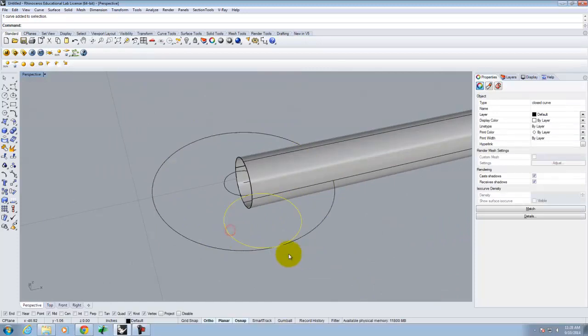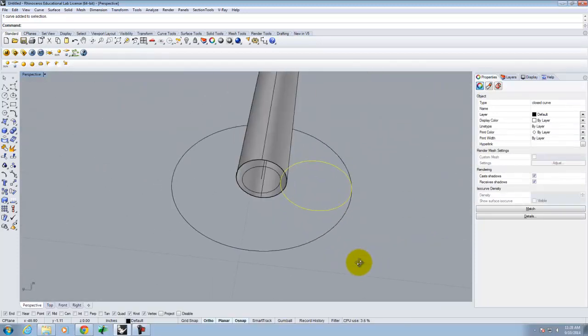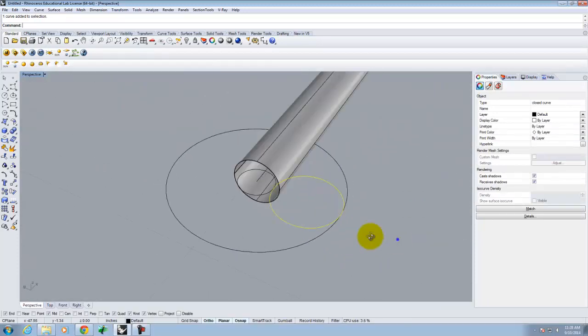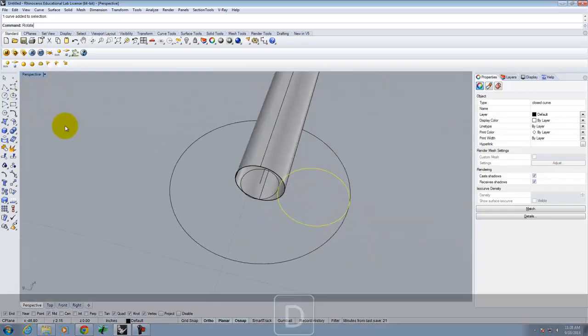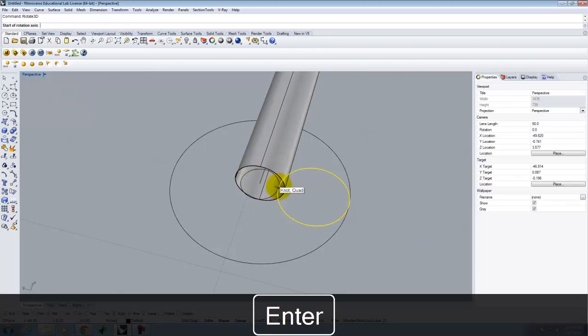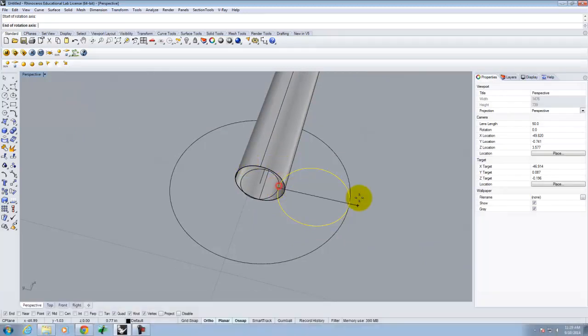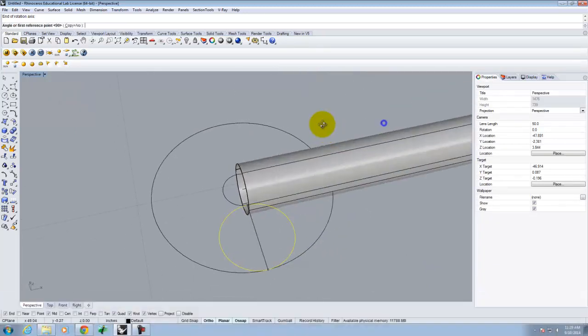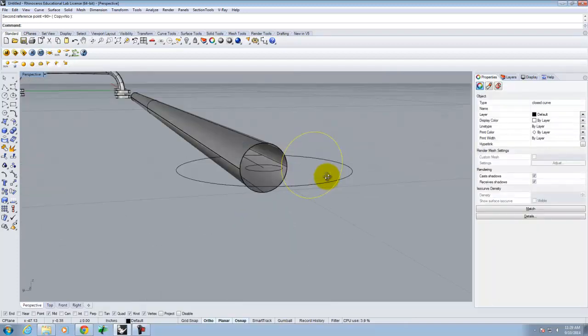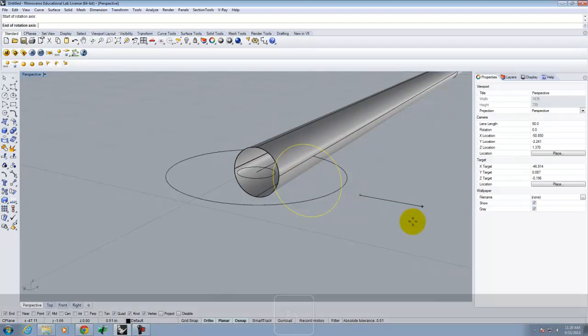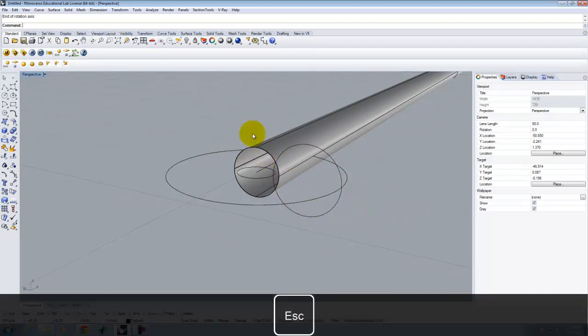Now, unfortunately, this circle isn't in the correct view just yet. It's not in the correct direction. So I'll use a rotate 3D to rotate this. We'll go from here to there, and we'll fold it up into 3 dimensions there. Now that I have this, I can once again do that sweep.